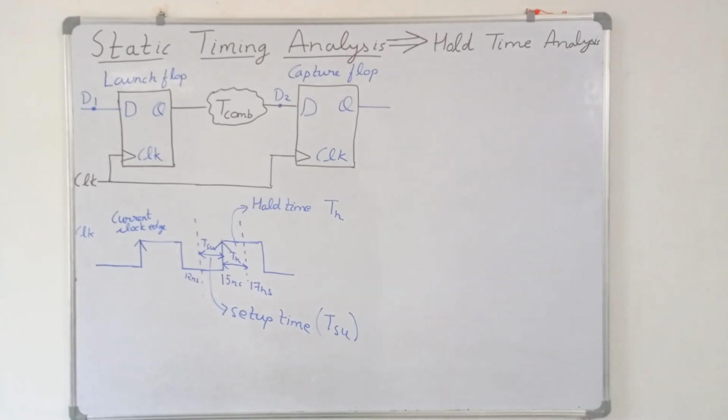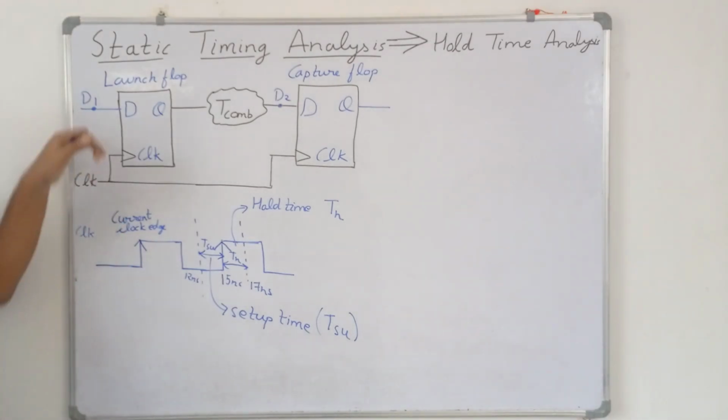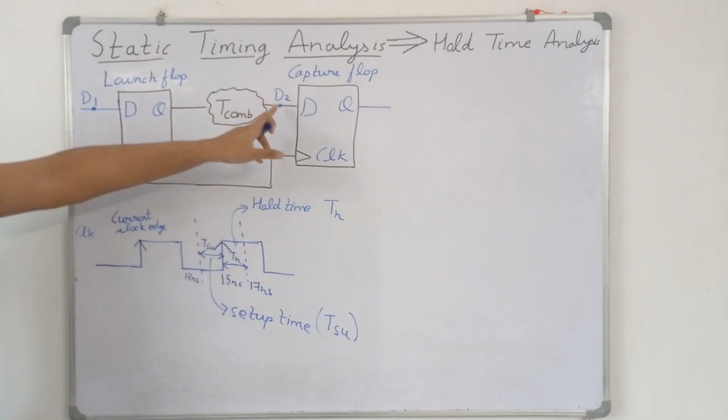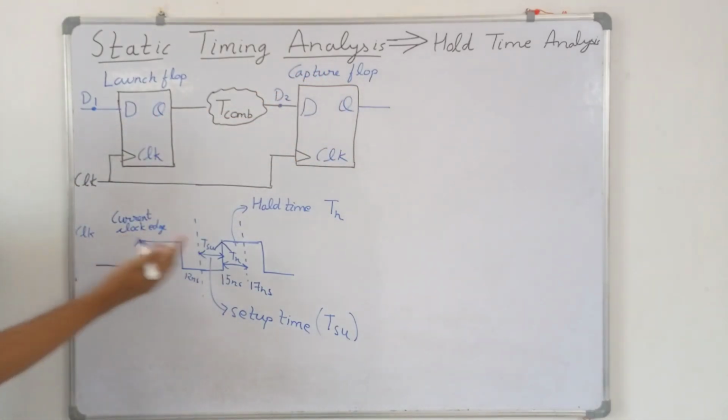Again I am repeating, in the setup analysis we have to ensure that the data which is launched by the launch flip flop at the current clock edge must be stable to be captured by the capture flip flop at least setup time before the next clock edge.